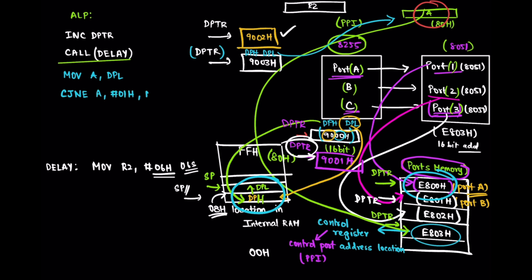And I'm going to jump to NEXT TST, which is the efficient checking mechanism of the loop, the inner loop. NEXT TST here is the inner loop. So I finished the inner loop here. So it is going to compare A with 01 and it is going to go back to the inner loop if they are not equal. If they are equal, it is going to continue below.